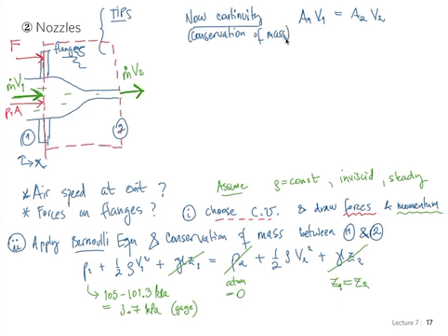So that means that I could now write this perhaps in terms of the diameters, because then the pi's cancel out, right, from the areas, and so I could write V1 D1 squared equal to V2 D2 squared. So what we're going to do is express V1 in terms of V2 so that we can put it back in this other equation here.